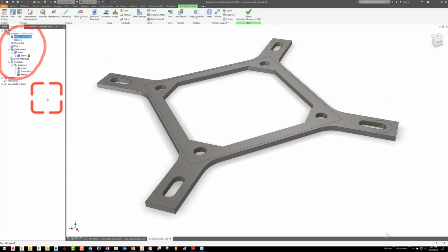Even if you plan to go on to something more advanced to make a nonlinear problem, it's usually a good idea to set up a static problem first and get a feel for the problem. So it picks that for us. We can switch it at any time. It's also created our first idealization. So what is that? This solid 1 is the idealization it's created.